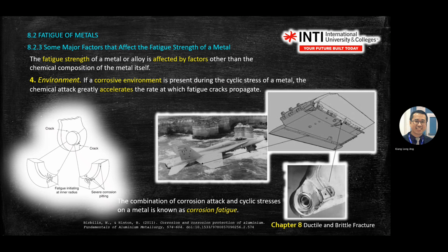Okay. So the crack will happen. There's a hinge on the wing here, right? This small thing where they can hook the missile or something, right? So the crack happens at all these corners. And if you observe carefully, most of the engineering design, we like to use a round shape. Because round surface, mathematically, it can help to distribute the stress.